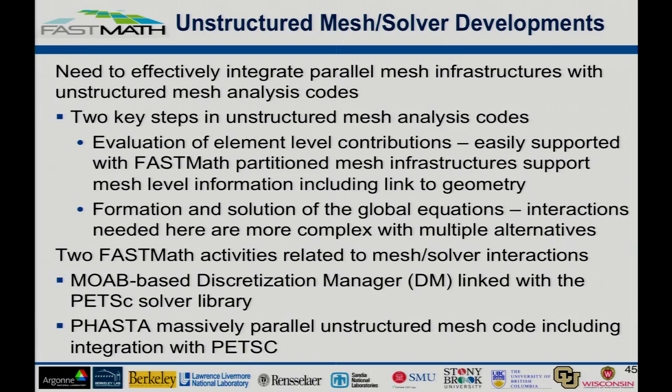So once you have created unstructured mesh, we dump it into a file with the partitioning information. We got to load it back up into an application, and what sort of interfaces are available. So I'm going to briefly look at two specific application areas. One is related to the Sigma tool that we talked about more about MOAB and its interface to PETSc. The other would be FASTA and its use of the unstructured meshes and also its integration with PETSc.